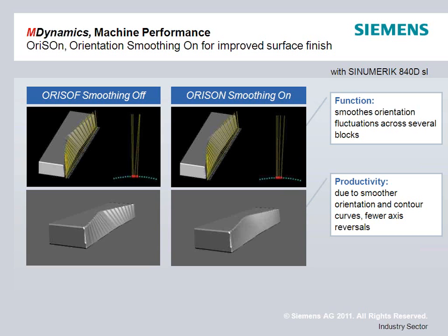The problem is this caused a little bit of a deviation on the part program, on the part surface, as we're moving from one point to the next to deal with each deviation from point to point. Now, obviously this causes a bad part surface finish. The other thing that we have to keep in mind is that this is a 5-axis function. When you're dealing with a 5-axis machine, even though this may be a very, very small deviation,